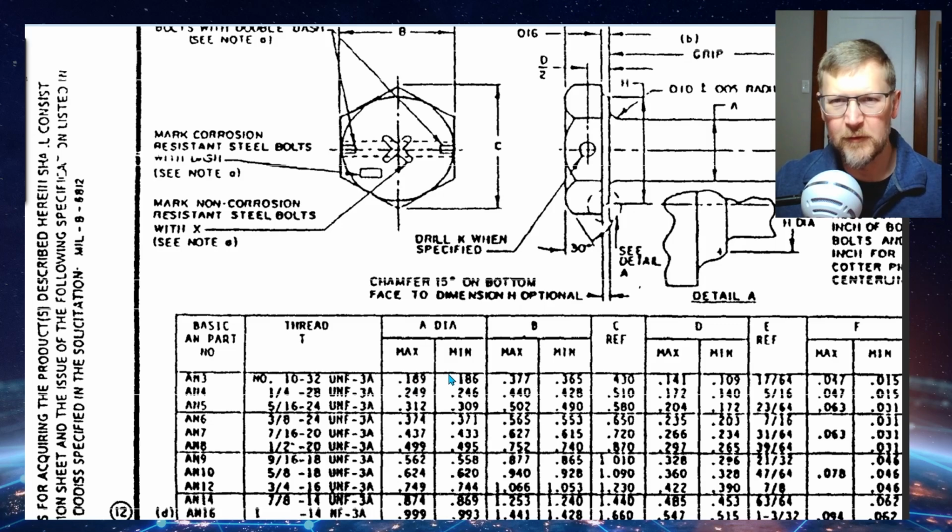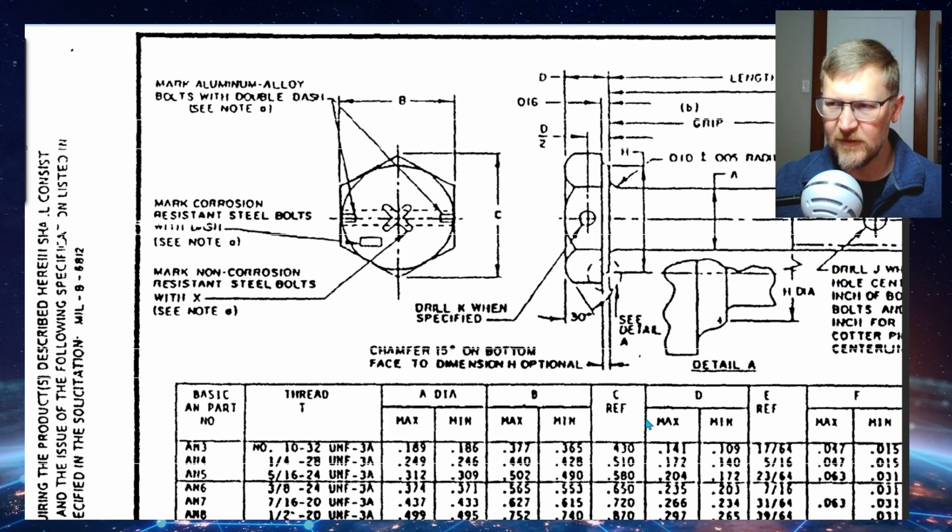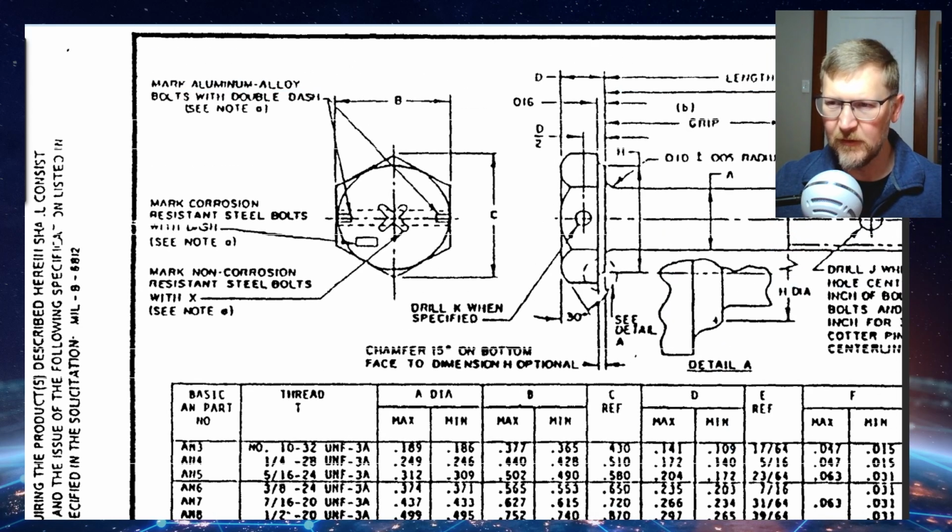The other thing, of course, is that most of those government specs are now transferred to other commercial or industry organizations, so this fastener spec is technically superseded by a more current NAS, National Aerospace Standard, spec out there, but for educational purposes, this is plenty good enough. If you are working in a professional environment, you should probably pull the latest specification to be sure you have the correct data. But in any case, this is just a standard bolt, so I'm not too concerned here.